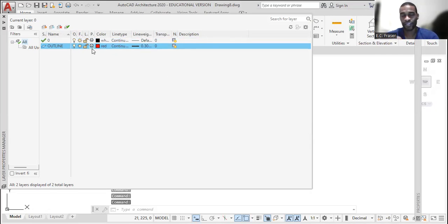So you will realize that you have set up your layers and you're ready to print. But when you go over to page layout, you realize that only some colors are visible. You're not seeing some of the colors. This is the problem right here. This was ticked either by accident or by some other means. If this is ticked, it will tell the computer that you do not wish to print that layer. So the computer will not generate that layer on the print format.